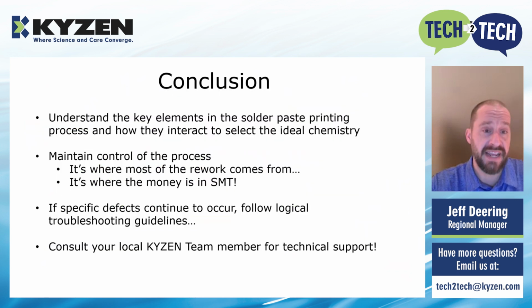In conclusion for today, it's important that we understand the key elements in the solder paste printing process and how they interact to make sure we select the ideal chemistry. After we do that, it's pertinent that we maintain control of the process. It's where most of the rework comes from, and it's where the money is in SMT. Keep in mind, if specific defects continue to occur, follow logical troubleshooting guidelines. And when push comes to shove, make sure you consult your local KYZEN team member for technical support.